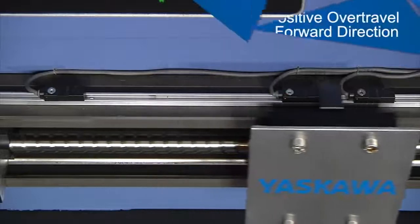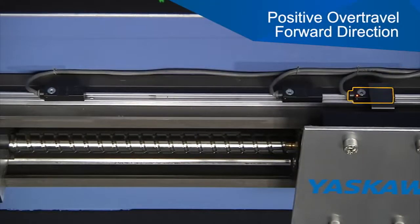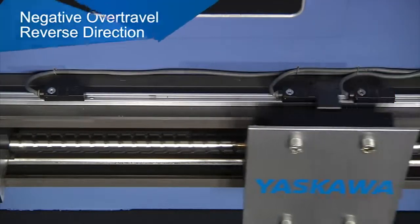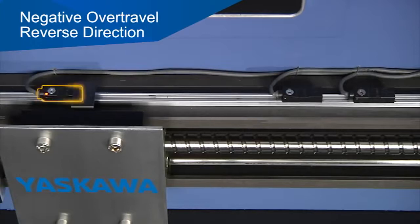Now, the positive overtravel sensor is connected to the amplifier input that stops motion in only the forward direction. The negative overtravel sensor is connected to the amplifier input that stops motion in only the reverse direction. So you can see that if these sensors get switched around, or if the direction of the servo doesn't match the direction of the machine, the motor might not stop at the overtravel sensor. Damage or even injury might result.